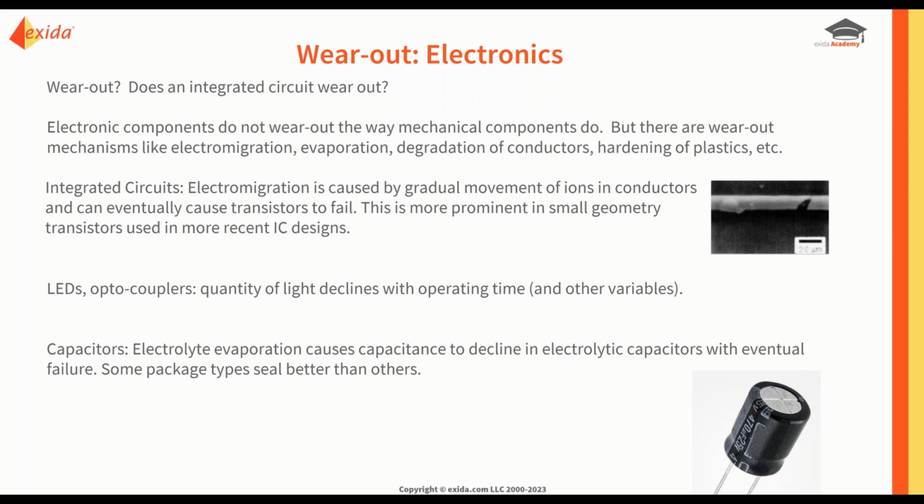So I saw a data sheet from a major semiconductor company for a microcontroller, a CPU with lots of peripheral circuitry all on one chip. And it said right in there, useful life, 10 years. And I thought, oh my goodness, 10 years? I mean, that's okay, I guess, if you're designing a cell phone or maybe even a laptop, a consumer product, but a lot of industrial process products are expected to run at least 20 years.